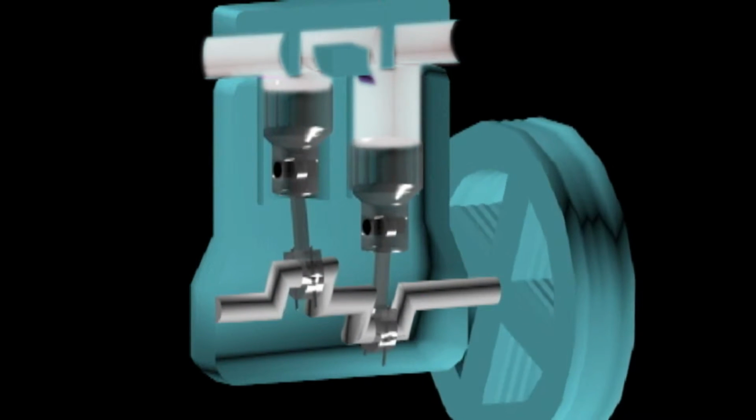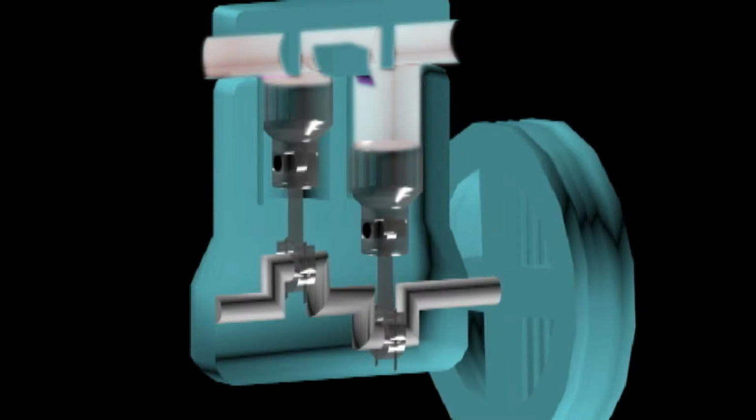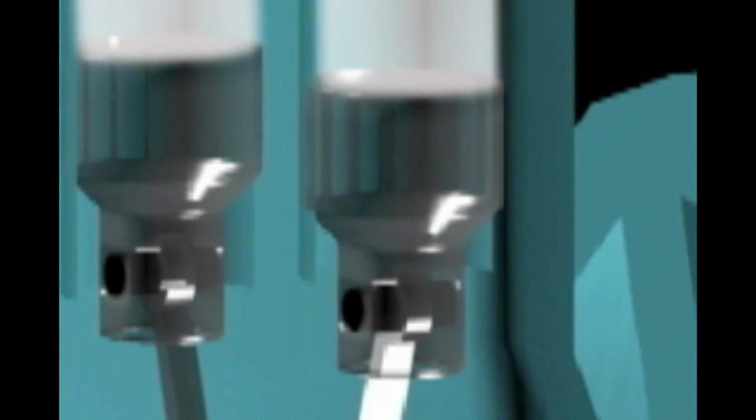The compression stroke will take place when the piston moving upward. During the stroke, the pressure rises to slightly above the discharge pressure and will cause the plate-type discharge valve to open. The refrigerant passes through at approximately constant pressure and flows to the condenser. At the end of the stroke, the differential pressure across the valve aided by the valve spring will close the discharge valve and another suction stroke begins.